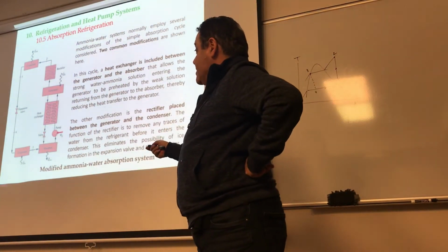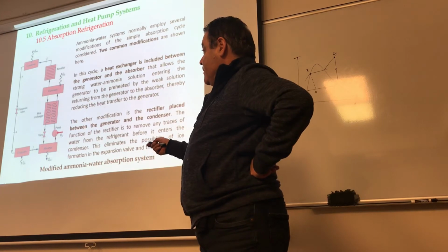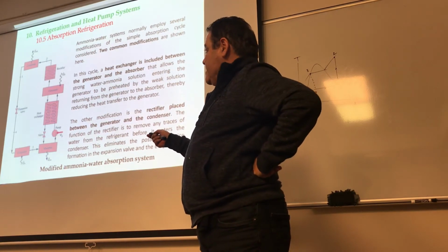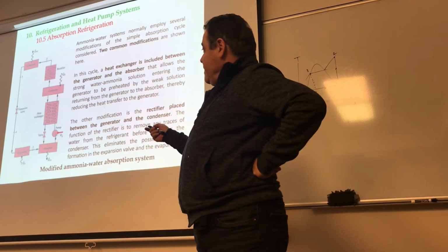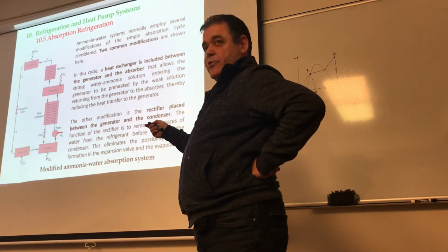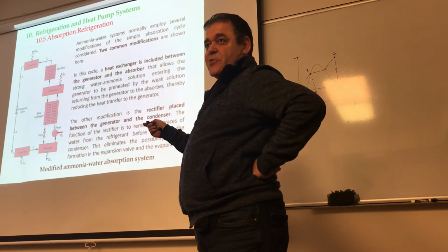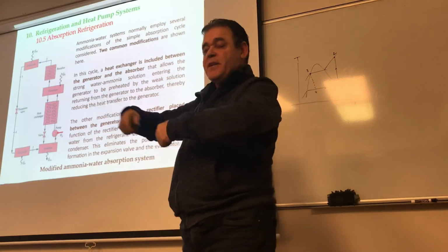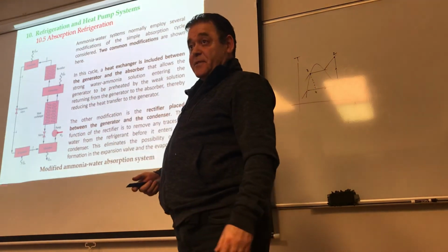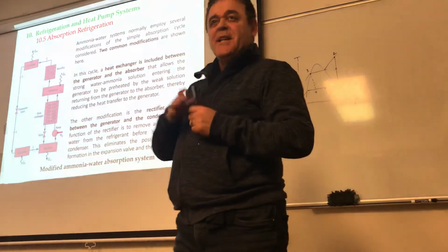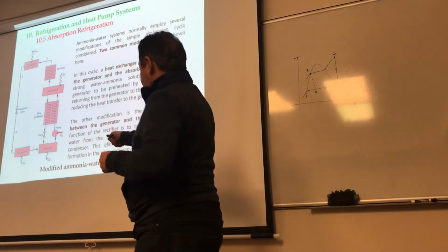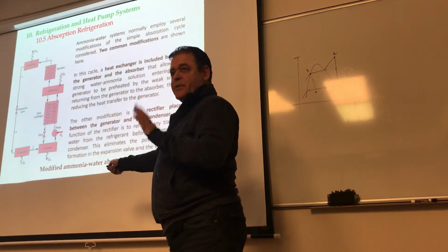Now the stuff that you're pumping from the absorber gets passed through this heat exchanger. So what's the benefit, you may ask? Well, the benefit is that you're not going to be putting in as much Q in here to separate the two. At least you are using a portion of that heat from something that you would otherwise just be throwing out. It's all about savings and efficiency. So this heat that would go here would just go out, period.